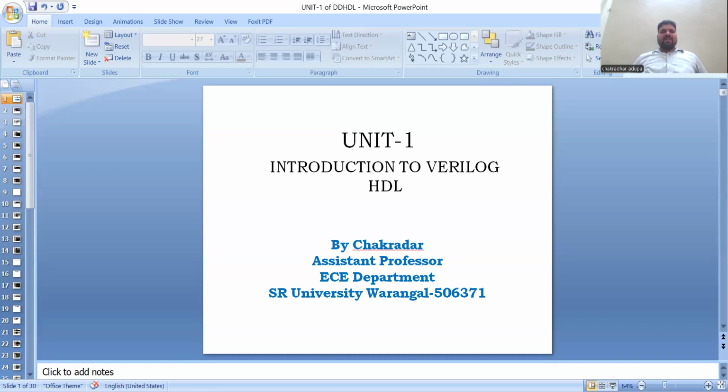Keep the stimulus and design block separate. The stimulus block can be written in Verilog. A separate language is not required to describe stimulus. The stimulus block is also commonly called a test bench. Different test benches can be used to thoroughly test the design block.